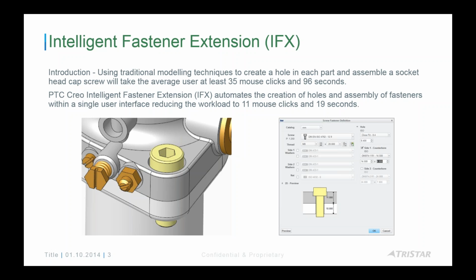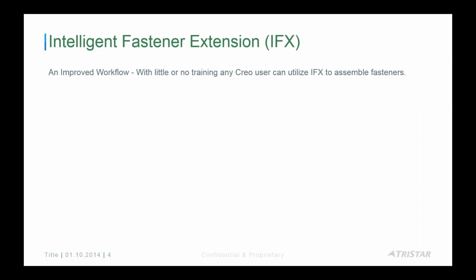Using the Intelligent Fastener extension, this automates the creation of holes and assembly of fasteners with a single user interface, reducing the workload to 11 mouse clicks and 19 seconds, approximately. This is an improved workflow. With little or no training, any Creo user can utilize IFX to assemble fasteners.